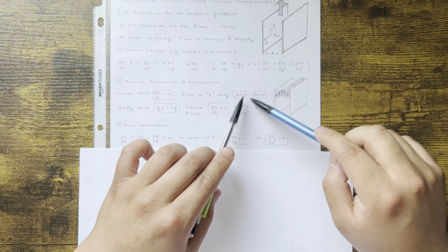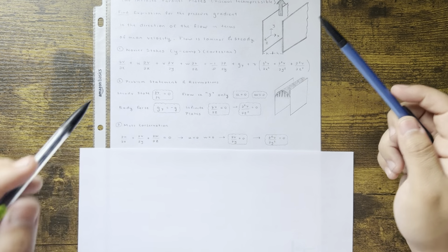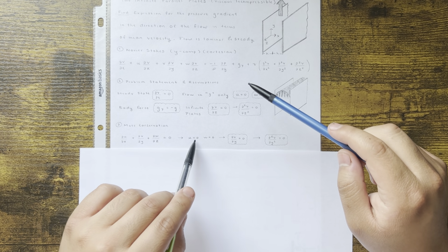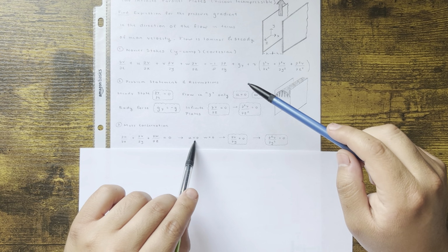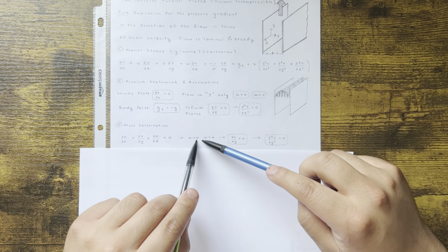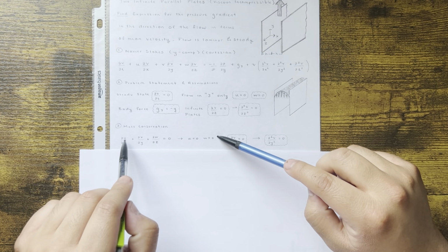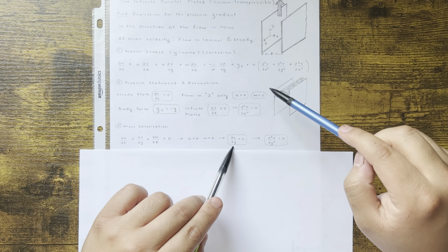But we know that u and w are 0. So anything in the x and z, there is no velocity profile. So that's just 0. So take the derivative with respect to y, right, for delta v, delta y. I'm sorry, delta u, delta x. Take the derivative with respect to x, you get 0, because the derivative of 0 is just 0. Same thing for w. So this term goes away, this term goes away, so now you're just left with this is equal to 0. So that's what you get here.